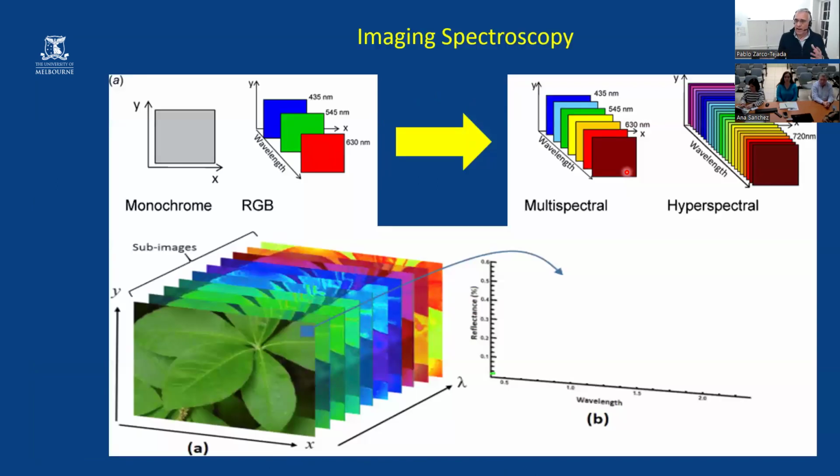And again, for people who know about remote sensing this is probably not needed, but just to put it in context: when we collect data with our cell phone, we get the three basic spectral bands, blue, green, and red. If we use multispectral cameras, then we get a number of spectral bands, 5, 6, 7, maybe 10, 12. That is usually the maximum number of spectral bands at specific spectral regions. If instead of multispectral, we collect several bands covering the full spectrum, then that is what is called hyperspectral imaging or imaging spectroscopy.